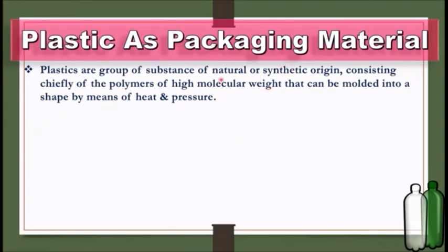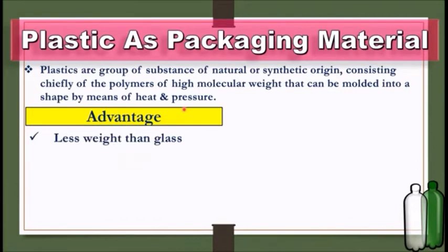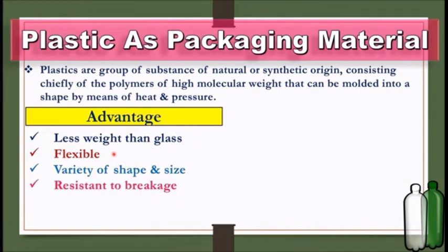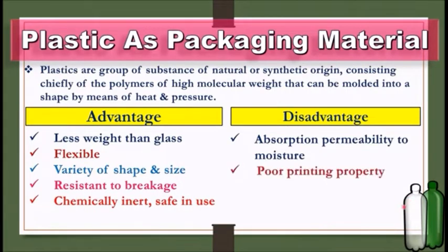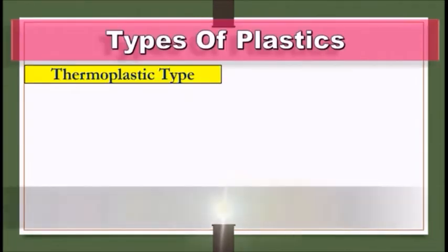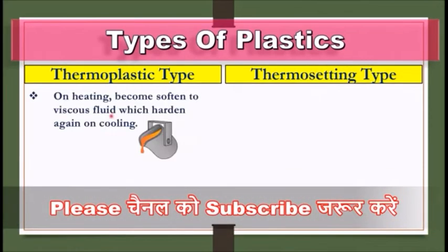Next we see the glasses as per their types in detail. Type 1 is borosilicate. In that, the reaction is that sodium is loosely combined with the silica and it reacts with water at 10 to 15 parts per million NaOH along with traces of other ingredients. The addition of 6% boron reduces the reacting action to 0.5 parts per million dissolved in the reaction in type 1 borosilicate glass.